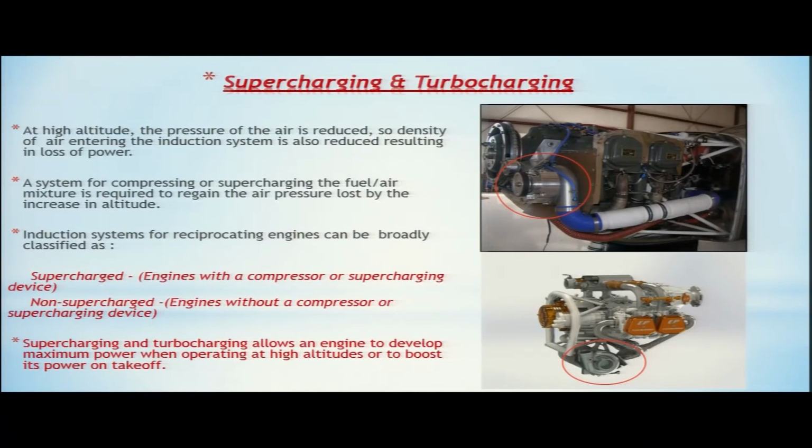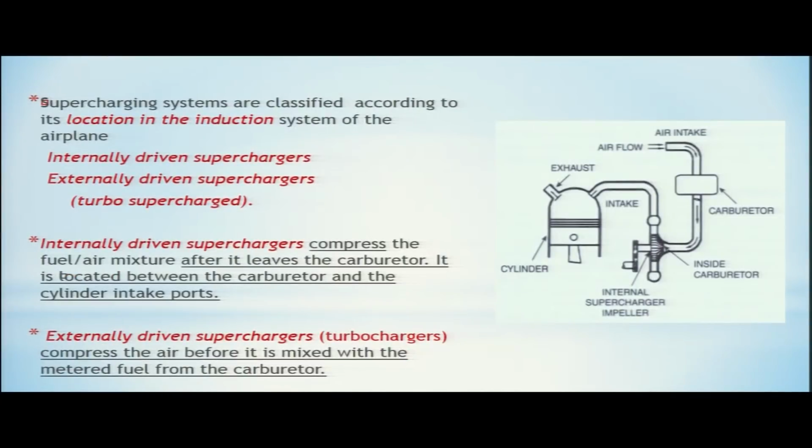We will see in our other slides that superchargers or turbochargers can boost the engine pressure at higher altitudes, or they can also boost the pressure during takeoff. Supercharging systems are classified according to their location in the induction system of the airplane.